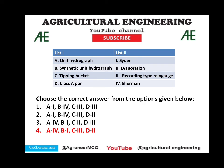So the tipping bucket is part of the recording type rain gauge. After that, class A pan, of course the pan evaporimeter, is used for measurement of evaporation, so the answer will be evaporation. And the synthetic unit hydrograph is Snyder, and the unit hydrograph is measured using the Sherman formula.